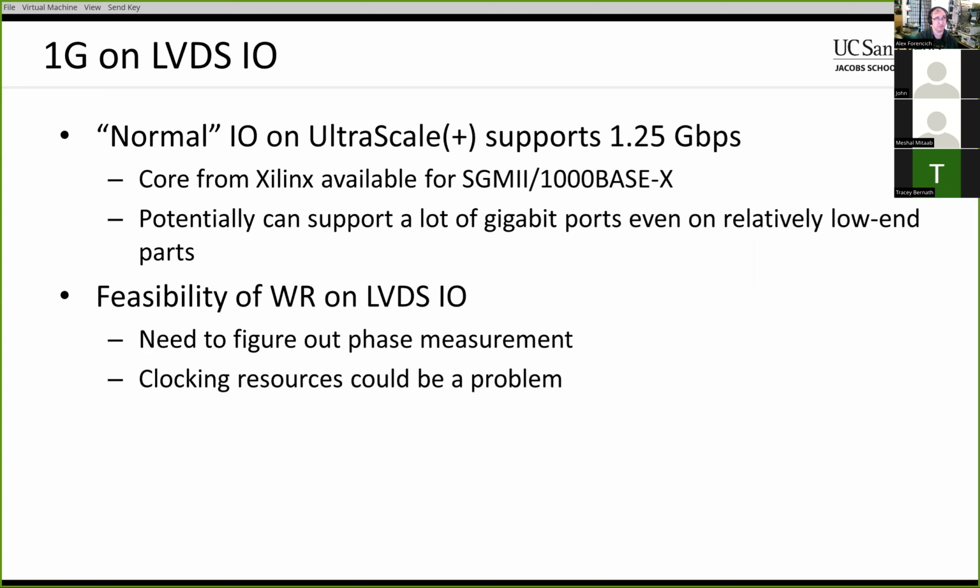So what does that work out to? I think that's what 12 ports per IOB. So you take something like the Kria K26 SOM. Can't remember exactly how many pins get pulled out of there, but something like 3 IOBs are actually exposed on the headers. So potentially you could support, what would that be, like 36 ports off of that thing, just based on the number of IO pins that are available.